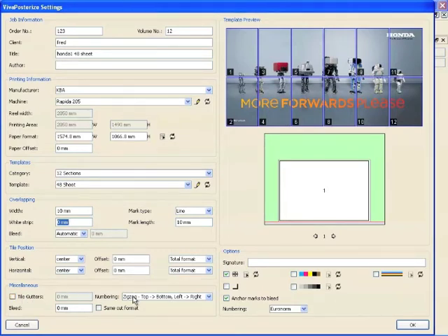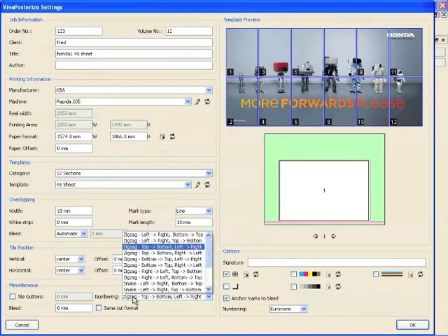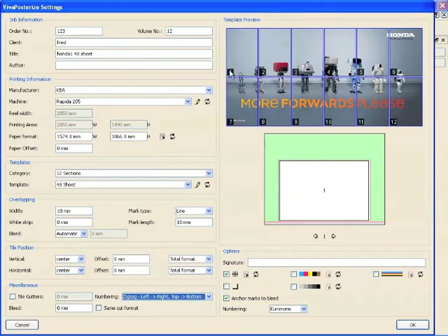The numbering of the sections is important, and in order to be able to supply sections numbered according to the requirements of all markets, we have a series of options that you can select. In this case, you would like to number your sections across the top 1 to 6 and across the bottom 7 to 12. So we will say left to right, top to bottom. And you can see that the numbers have now changed.